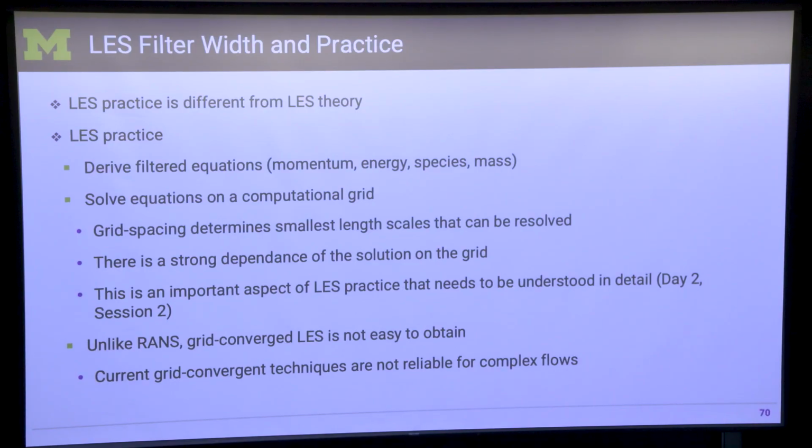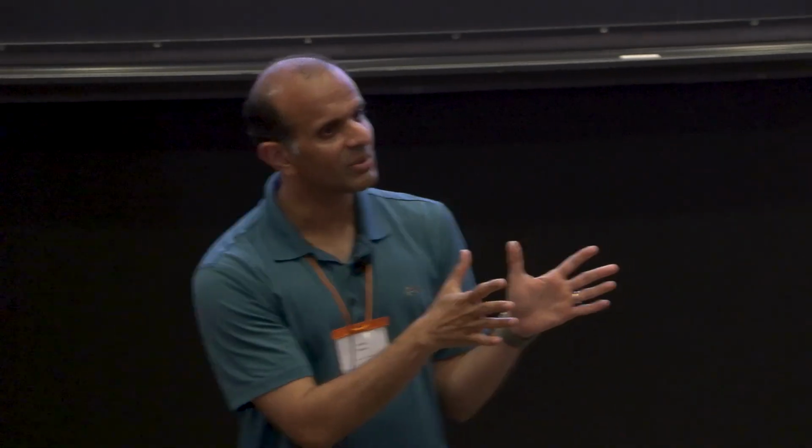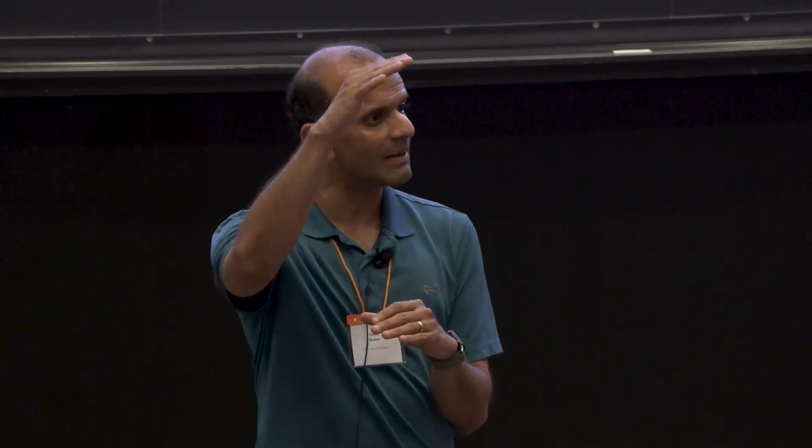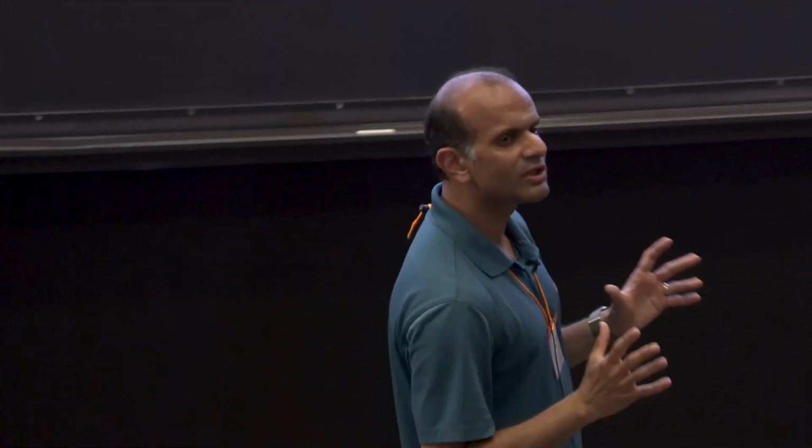I have this thing in the middle. Tomorrow we'll talk about this more on what are the limitations of LES. That's very critical. We started looking at it a little bit. So if you have the same boundary conditions and over time, if features inside change, then LES is good. But what is not good is that if you change the boundary conditions, the time it takes to adapt to the change, those features you cannot capture correctly. So for that, a little bit of nuance in how we think about this problem is needed. Yeah? So this is all I had for today.